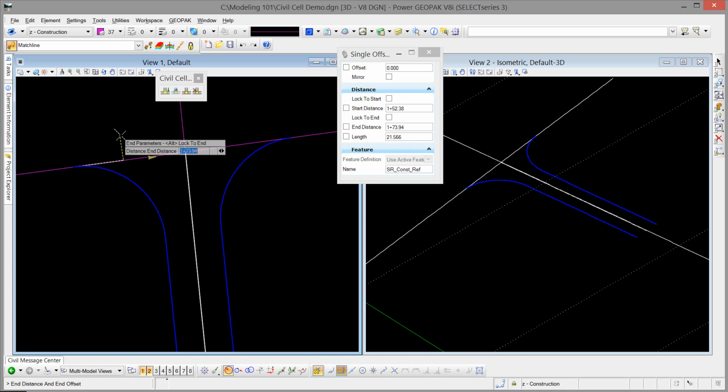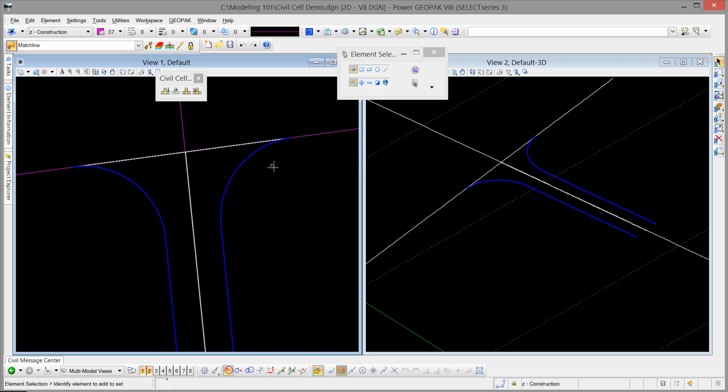Now we want to, again, if you toggle over to length or in distance, never use in distance station. Toggle to length, but it's not going to matter because essentially we're going to override length and allow it then to snap to this endpoint. So once it finds it and highlights it, and you have to be careful with your mouse, accept. Okay, we don't want to mirror, and now we're done. Okay, so we'll come out of our command.